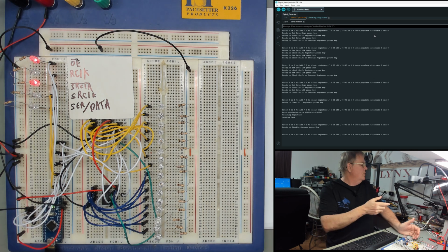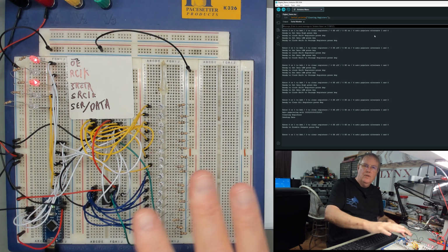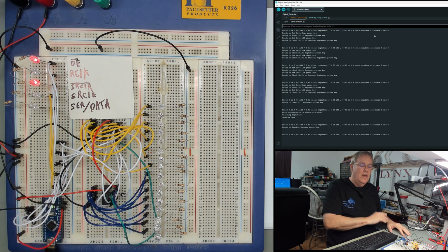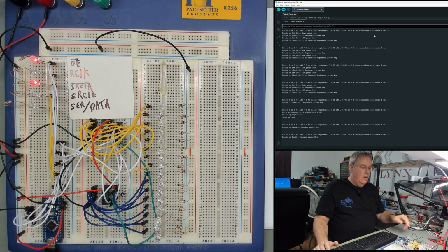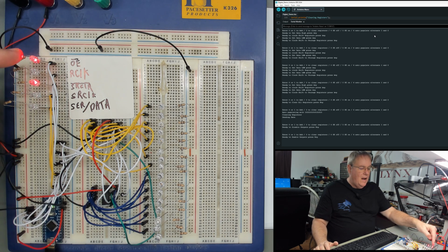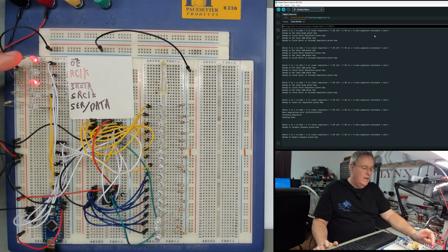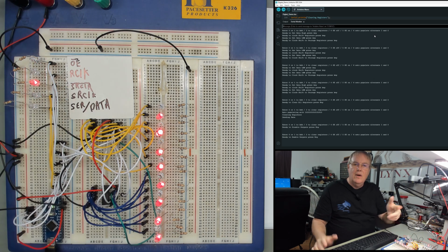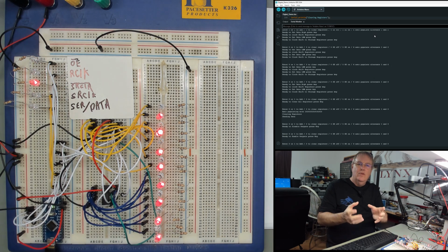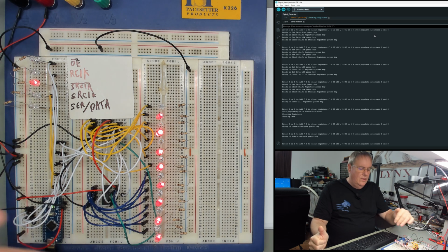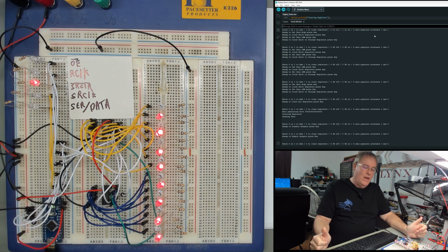Now, nothing's changed in the registers. They've all stayed the same. The data is just the way we left it. So if I now go in and instead turn the enable back on, so if I do 5 and enter, you're going to notice it drops from a high state to a low state on the OE, which is enabled when it's low. That's what the line above it means. Remember that. When it re-enables, you'll see that the lights will all come back on because those lines go active. Whatever's in the storage register now turns on. We changed nothing, so we have the same thing we had before.